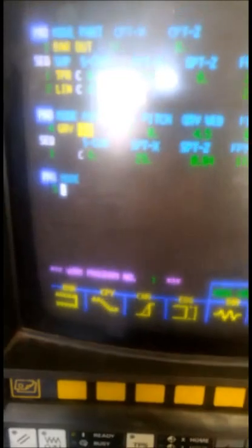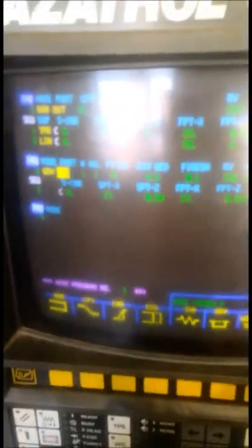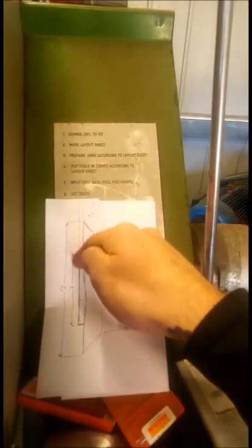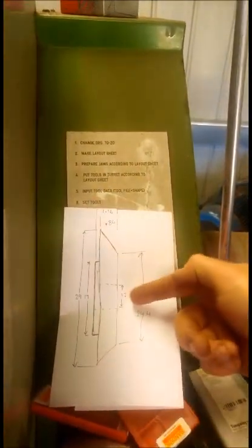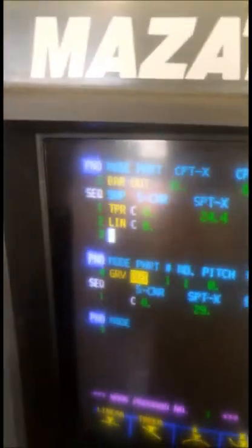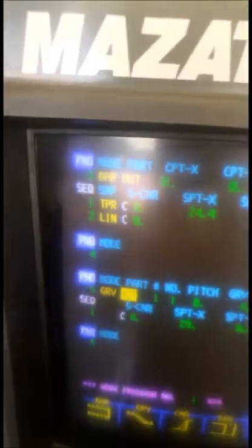And then we want to do, actually I'll throw this up in here, so here's another little bit to learn. If you want to insert a section, so what I've done, I've done my bar out and then my groove. So I've done that bit and then done down to that step. I actually probably want to drill the hole first, so it's got a little bit more stability. So I'll just go up to the start of this groove operation. Then if I go menu button, insert, and then hit input, it'll whack another bit in there. And then, because I'm done with that bar out shape, but I want to make a new thing, I'll just go shape end, and there we are on a new line.